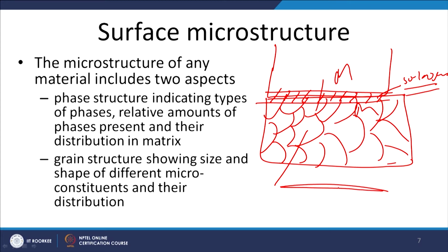It will be elongated, strained, broken down, refined, fractured. So, near surface layer structure during metal to metal wear conditions is damaged completely, and a new kind of structure is produced, which in turn actually determines the response to wear and friction behavior. But the initial structure of the base material affects the mechanical properties in general of the bulk material.